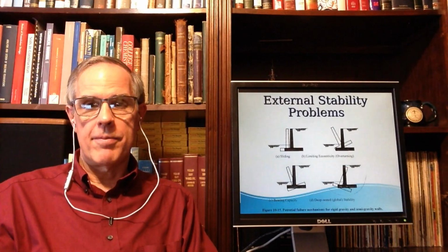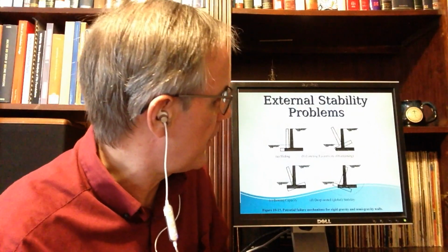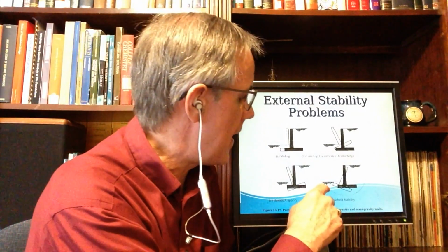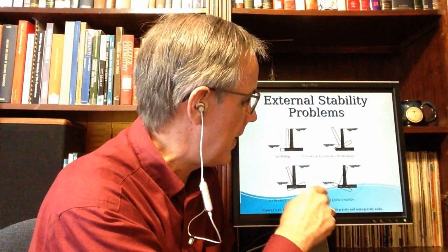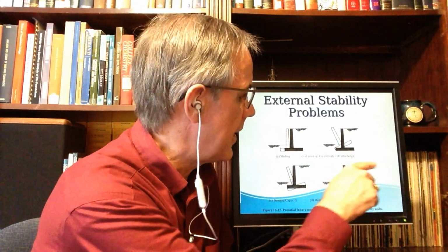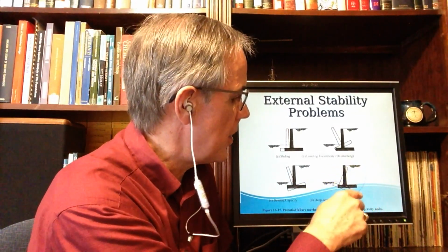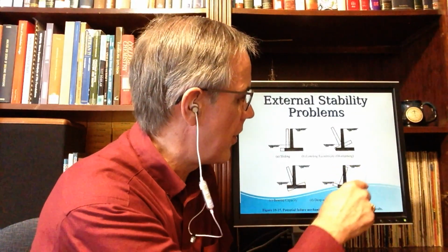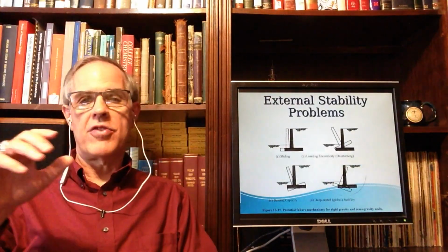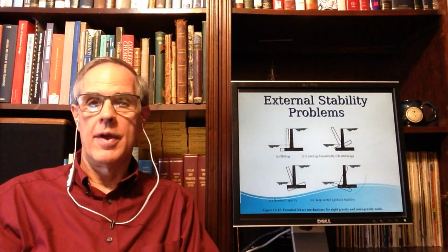And global stability. Basically, global stability means that the soil decides, I'll show these guys who's boss. It's basically like a big slope stability. In other words, you tried to make this into a retaining wall instead of a slope, but it decided to fail along a radius or a circle which is completely outside of the wall.